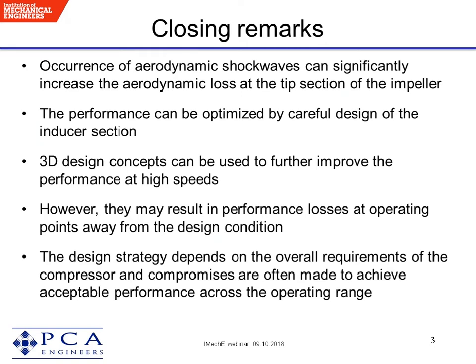The second part of your question is what considerations should be made with respect to modern manufacturing processes such as 3D printing and ALM when designing a perfect diffuser. Well, I would say, firstly, diffusers are difficult. A good diffuser needs a pretty sharp leading edge, and it needs a very accurately controlled throat area. So any way in which you can use modern manufacturing processes to improve those should give you a better diffuser.